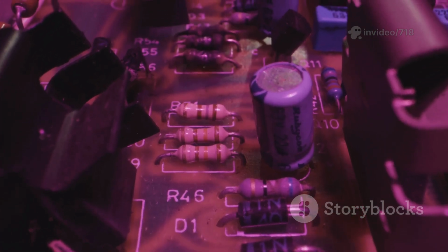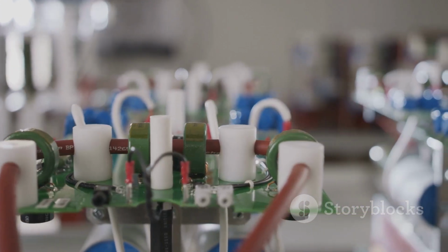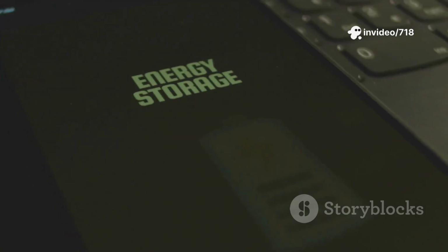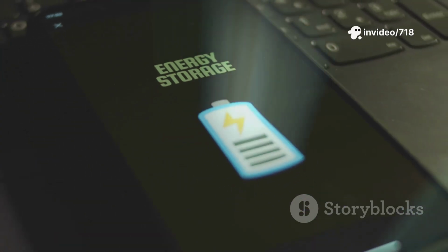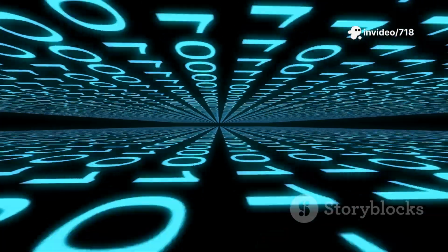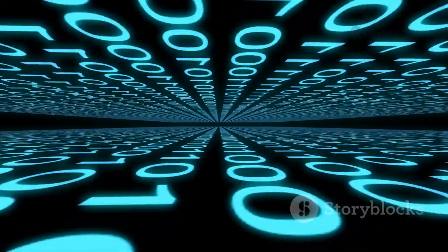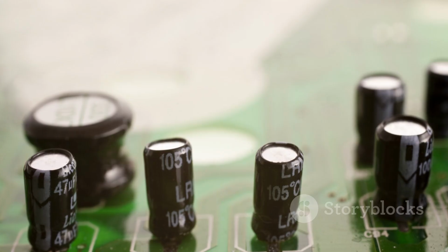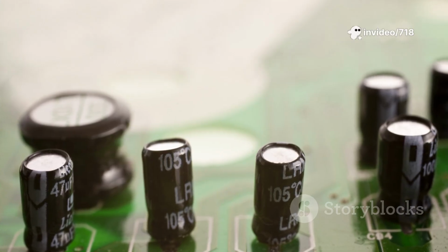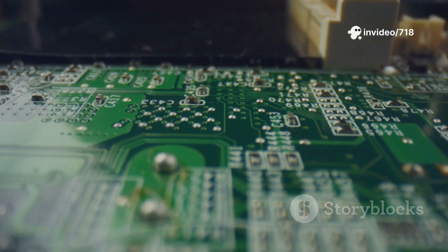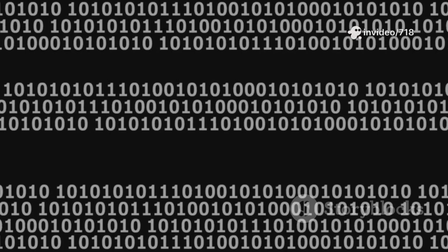Let's break down the 2 parts. First, we have the capacitor. Think of it as a microscopic, rechargeable battery, but one that can only store a tiny amount of electrical charge. Its job is to hold 1 bit of data. In the world of digital logic, everything comes down to 2 states: on or off, 1 or 0. In our DRAM cell, if the capacitor is charged up with electrons, it represents a logical 1. If it's empty or discharged, it represents a logical 0.